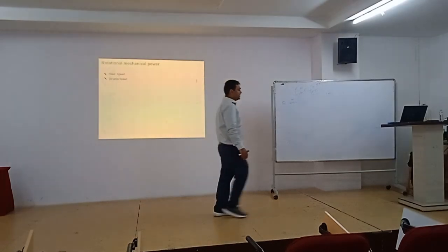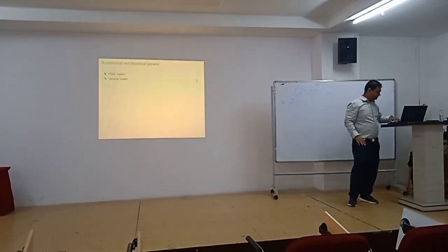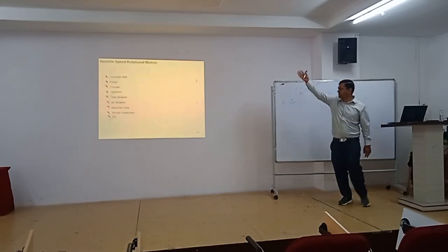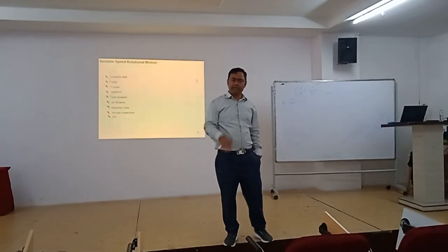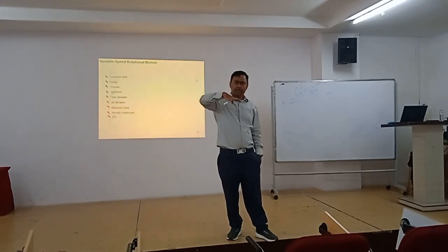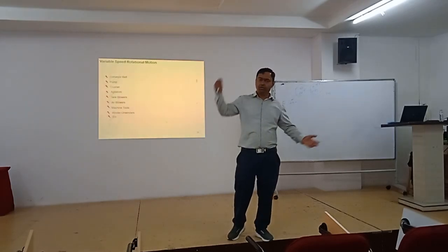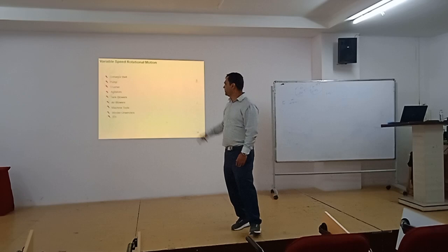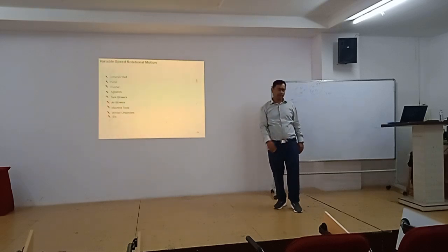And we have so many applications for variable speed, and the main product is the induction motor. These are the applications where you need variable speed. So many applications; these are just a few examples. We need a conveyor belt where we need variable speed. We need a pump, a crusher. You know the meaning of crusher, right? It crushes big stone into small stone. If the stone is heavy, you need to decrease the speed. If you go with more speed, the crusher will break. So you need very low speed. Then agitators, tank doors, machine doors, and many other things where you need variable speed.